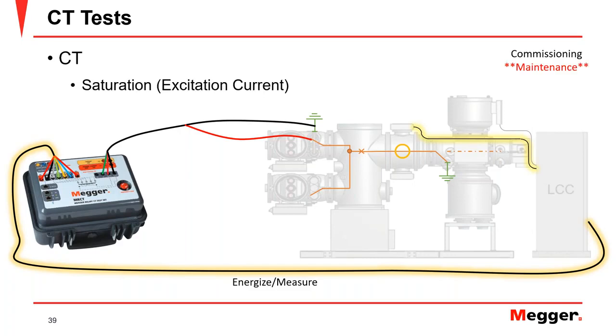For CTs, we can perform saturation. Once again, the unit will use the secondary leads to both energize and measure to perform this test, and we leave our primary lead connected just for safety reasons.